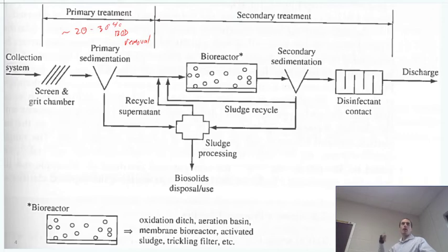So that's one of the most obvious metrics for our wastewater treatment: how much stuff that bacterial or biological activity will consume oxygen in order to eat, how much of that stuff have we removed? Because if we send all that into the environment, then the biological activity in the environment will consume a whole bunch of oxygen, and then we'll have oxygen deprivation for the fish and wildlife, and that'll be a problem. So one of the very fundamental things is BOD removal.